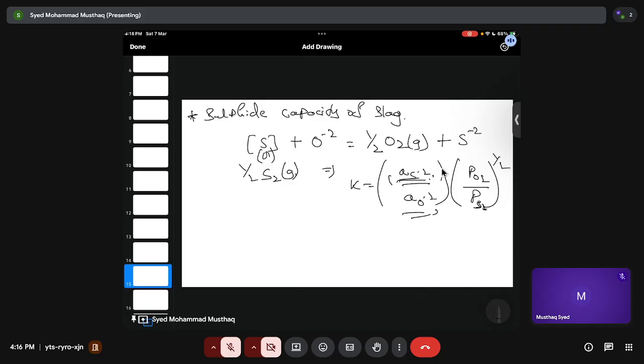So in most of your metal melts, you will not find a large amount of sulfur. It will be available in the elemental state in your liquid melt. You oxidize with your oxygen, and then it will form sulfur dioxide or sulfur oxide, depending upon conditions. Electrical and thermal conductivity, as I have said before, is very poor because we are talking about oxides and silicates.